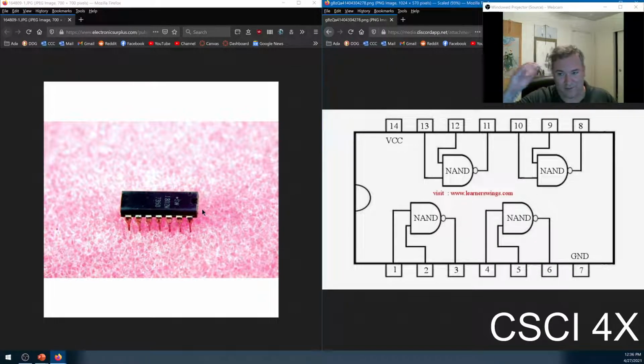So what the hell does that do? It just, high volts creates high volts and low volts creates low volts. Well, it's because you can have a completely different power system. Rather than your Raspberry Pi trying to source enough power to power a motor, which will usually drain enough power that the Raspberry Pi reboots itself, it's quite common. If you hook a motor directly up to a Raspberry Pi, it just boop, turns off and turns back on again, and your program stops running.